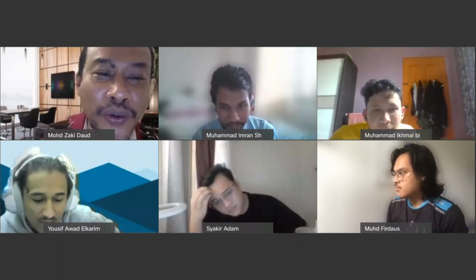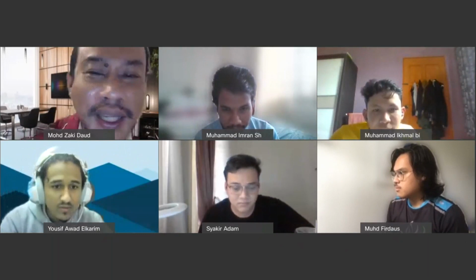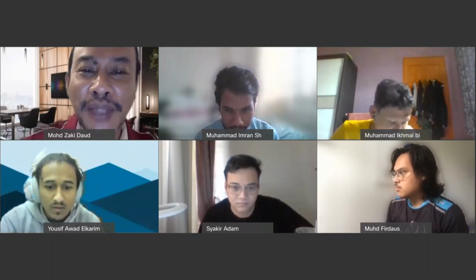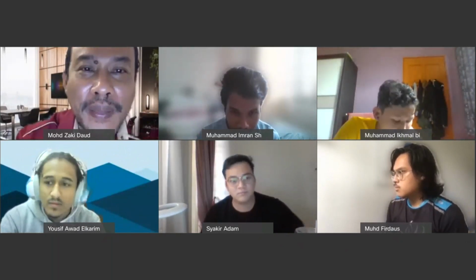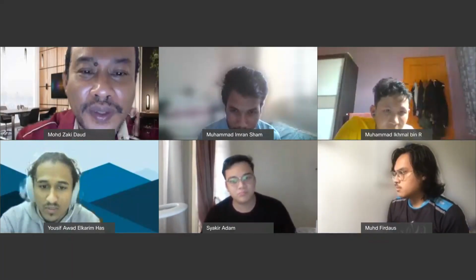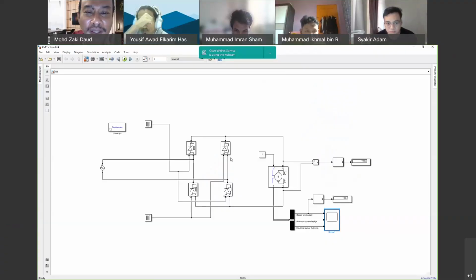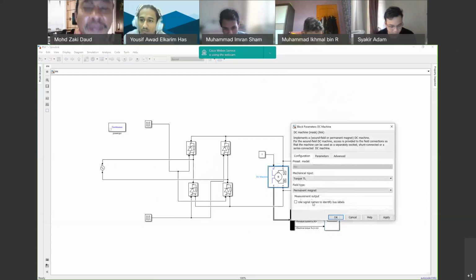I think you are doing very well. So Group 12, either Shakir or Yusuf, can you present something? Yes, doctor. I do the permanent magnet DC motor with a thyristor drive. We have to build the circuit. By changing the firing angle, you can change the input to the motor. Is it a permanent magnet or a separately excited motor? Permanent magnet, doctor. Okay. So can I see the waveform?